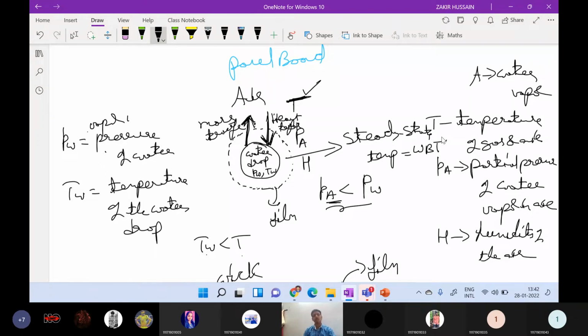Whatever temperature we measure under such condition is called the wet bulb temperature. So wet bulb temperature is nothing but a steady state or non-equilibrium temperature reached by a small drop or a small mass of liquid exposed under undersaturated, adiabatic condition. It is led to be saturated, and led to be occupied by the continuous stream of gas. Then only the steady state temperature attained by this continuous gas phase is called the wet bulb temperature.